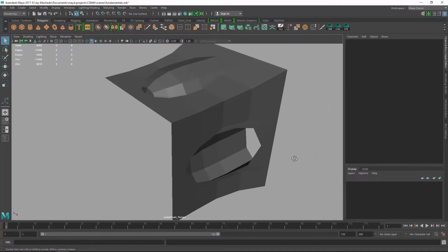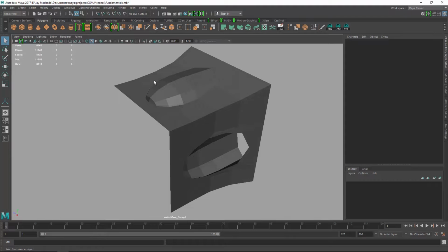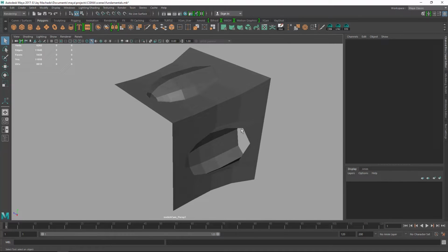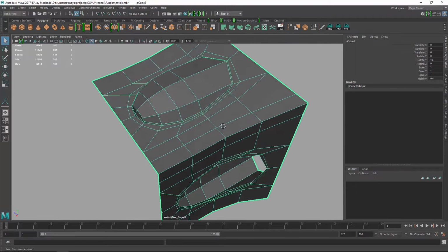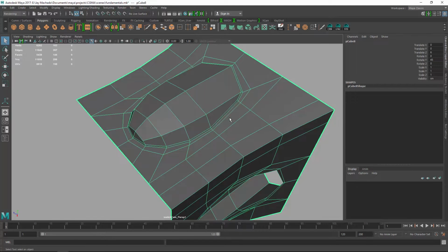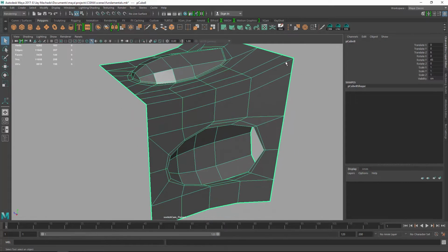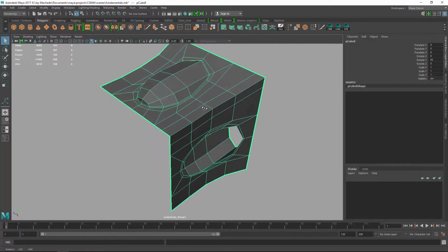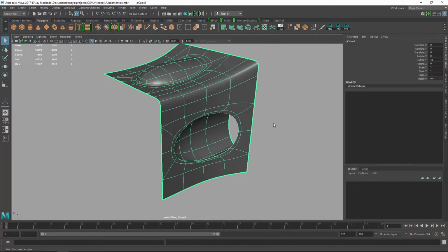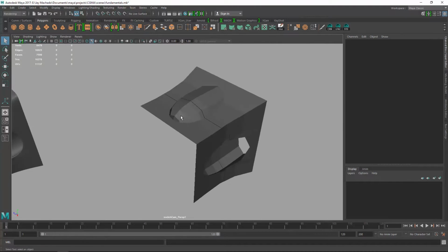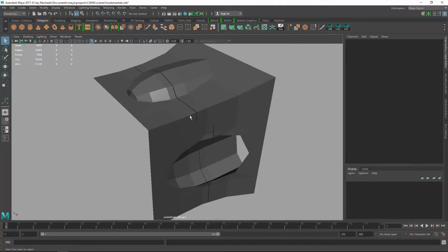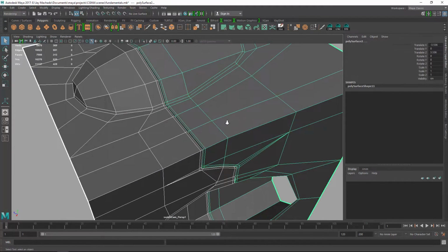Here's an even more complicated shape where a pill shape is protruding from this top surface and also carving out this lower surface. The challenge here is supporting these edges where these shapes intersect while simultaneously maintaining the curvature of the main surface, so when you smooth it, nothing really looks out of place. To complicate this even further, I have this same shape, except I've carved a part line out of it.